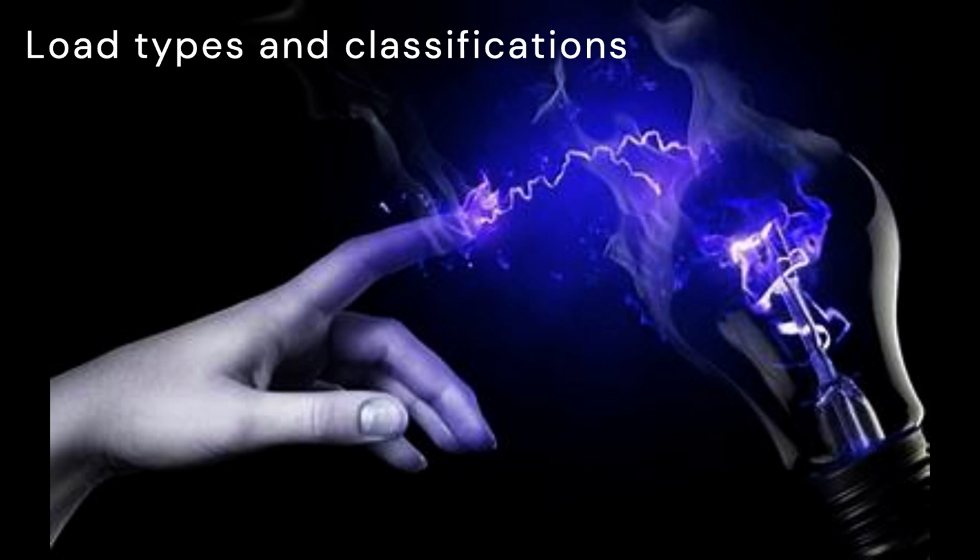4. Feeder loads. Feeder loads pertain to the total load on a feeder circuit that supplies multiple branch circuits. The calculation of feeder loads involves aggregating the connected loads of all the downstream branch circuits. Feeder loads consider diversity factors since it's unlikely that all branch circuits will operate at full loads simultaneously. Accurate determination of feeder loads ensures that the feeder conductors and overcurrent protection are appropriately sized.